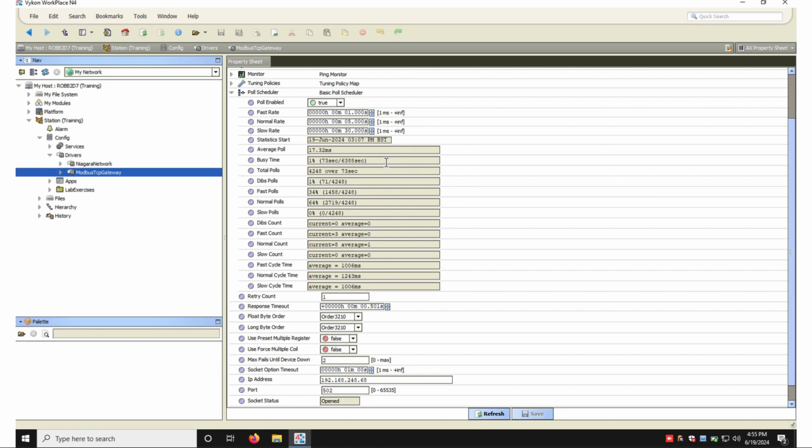Okay, so link marking, histories and alarms, we do want to really start to think about this polling rate. So if we're just interested in histories and we're only logging the history once every 5 minutes, is there any mileage in polling the point every 5 seconds? Probably not. Maybe once a minute would be okay. But if we're using that value for logic processing or graphics, we may want the point to poll more frequently, so the screen is updating more often. You've got to get the balance right, and it'll be a bit of trial and error based on the busy time.